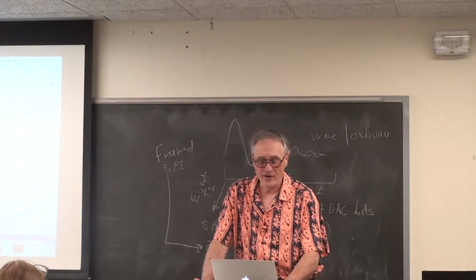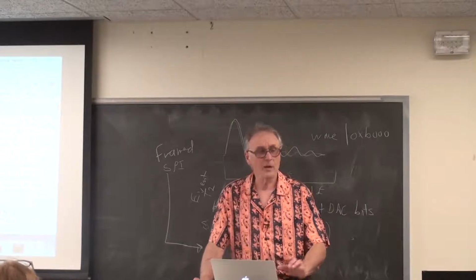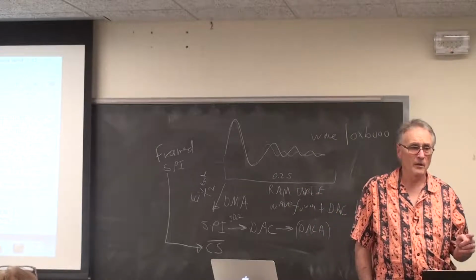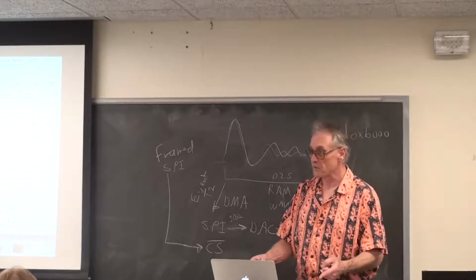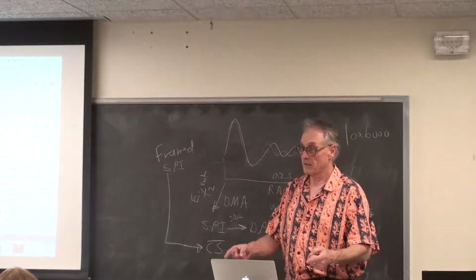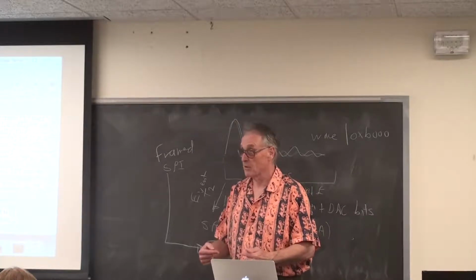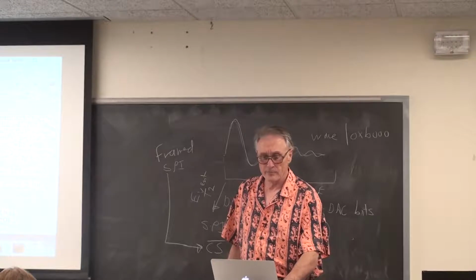By way of trying to figure out frame mode, I wrote a frame mode version, but I used an interrupt service routine to run the frame mode, because I don't want to give everything away. You cannot use an interrupt service routine. This is for the framed example. You have to convert the framed example to DMA.